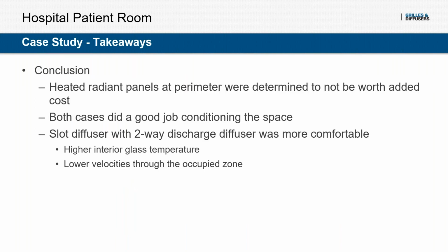So what are our main takeaways from this patient room? Based on our mock-up testing, it was decided that the radiant panels were not needed. They were not worth the cost, and both the first and second alternative did a good job at conditioning the space. Although it was decided that the second alternative was more comfortable, so we would typically recommend this layout.